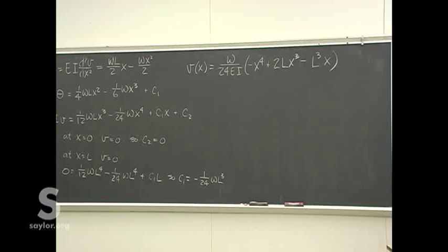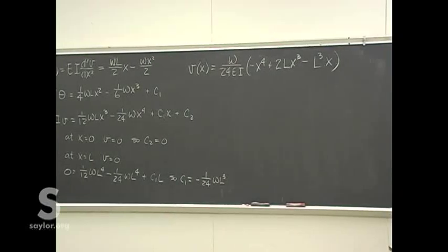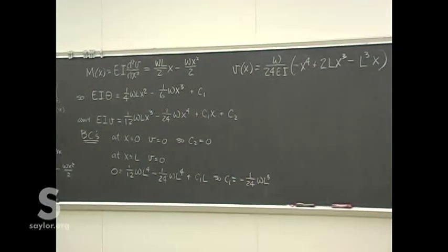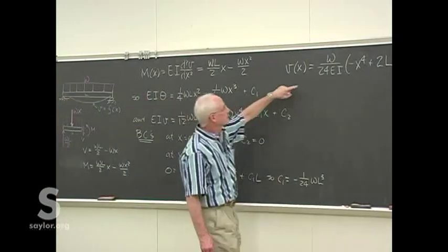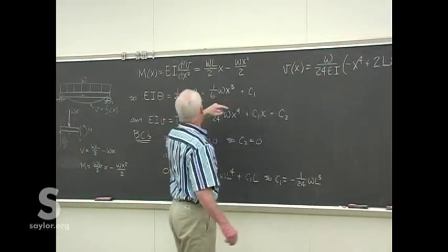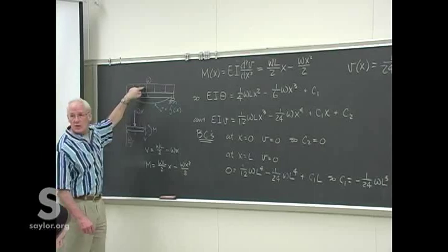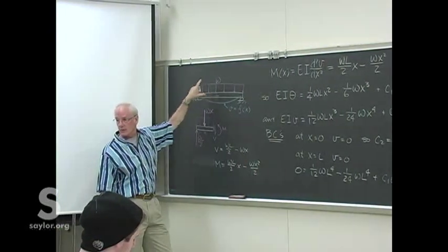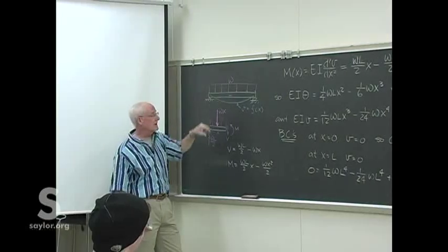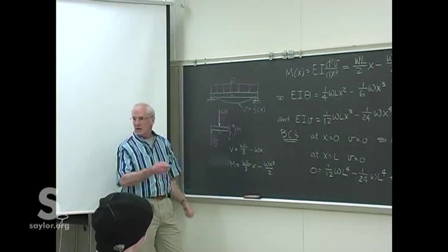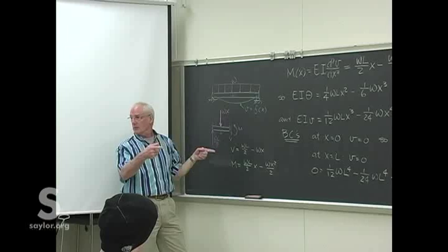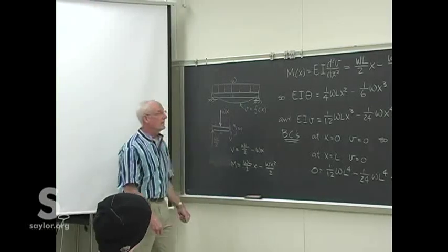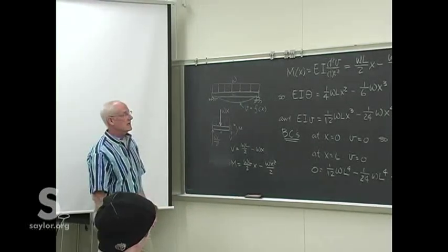Okay. And so now we can calculate the actual deflection. The uniformly distributed load, well, we can go into those beam tables we used the other day, pick a beam right out of there. Remember, one of the values given there is the linear weight of the beam, right there in the beam designation.